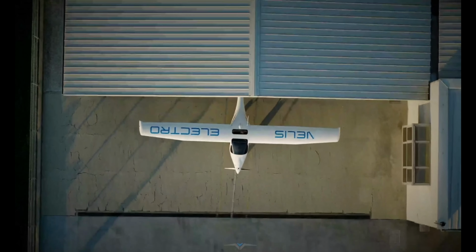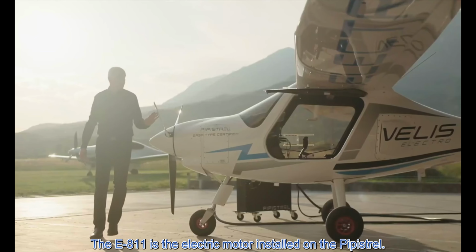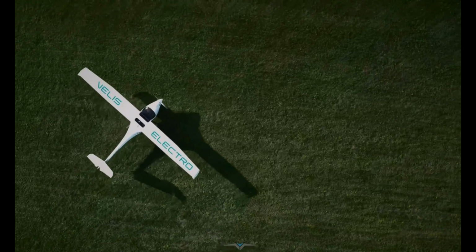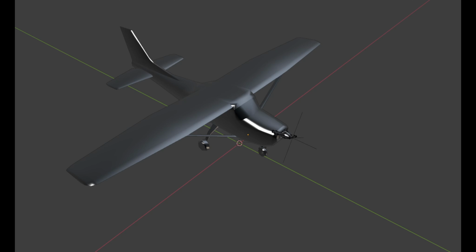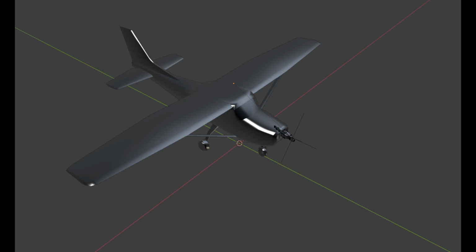One point to clarify is that I do not know the exact acceleration profile of the E811 electric motor. Therefore, in my simulation, I assume that the propeller has already reached its maximum rotational speed before the aircraft releases the brakes. This means the initial velocity is 0, and the initial thrust is about 2,050 newtons, corresponding to the stable thrust at maximum RPM.